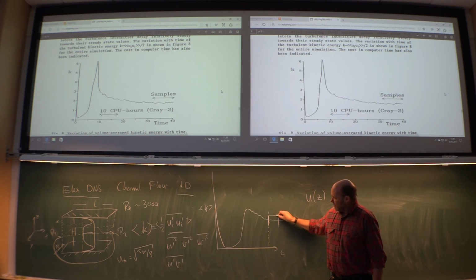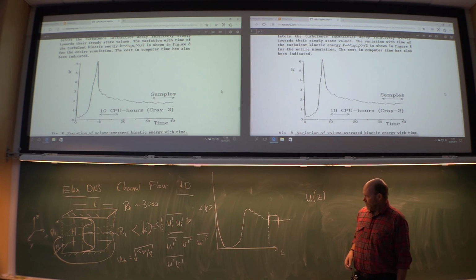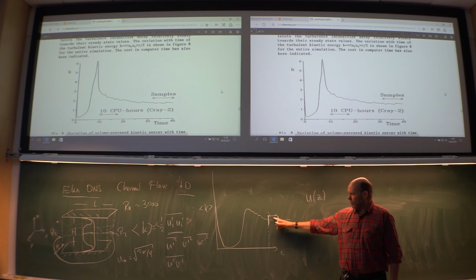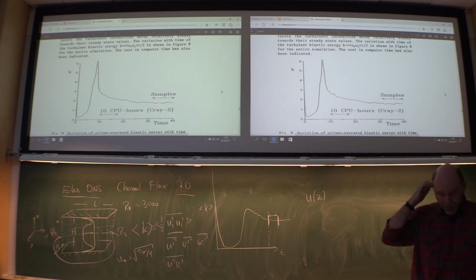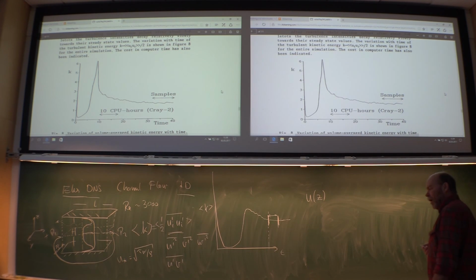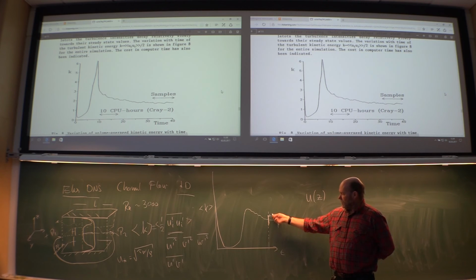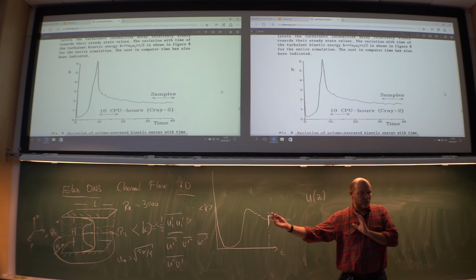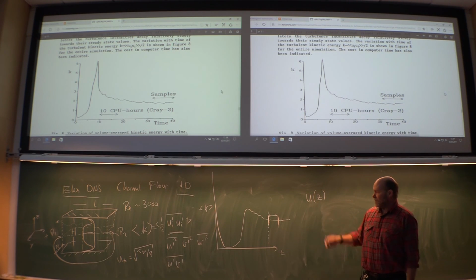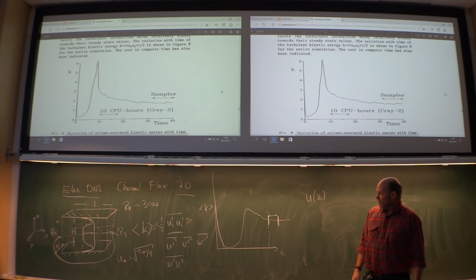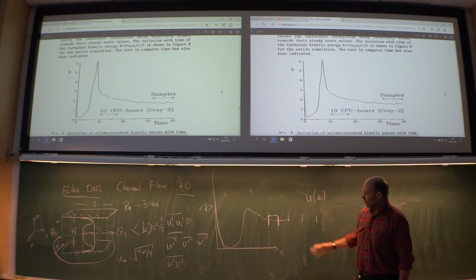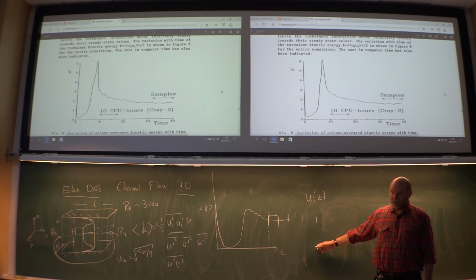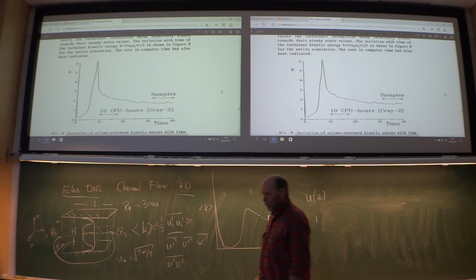It's not worth the effort to take every time step, because you have very small changes from one time step to the next. So the solutions of the Navier-Stokes are going to be quite similar, highly correlated. You have to wait until, say, 100 or 1,000 time steps before you take another sample. Then you have a totally different solution. They must be uncorrelated, or else the statistics won't be worth anything. So you need different solutions, and you need many of them. Of course, the more you need, the more expensive it's going to be. You have to simulate for a very, very long time.